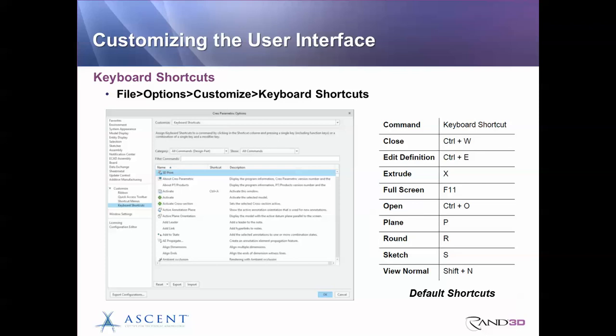There are some enhancements to your keyboard shortcuts, the ability to access some more standard keyboard shortcuts like edit definition, for example, Control E keys. You'll find quite handy in Creo 4.0. You can customize your keyboard keys if you like, and you can still create your own keyboard keys or Mac keys and add them to your environmental config.pro file.